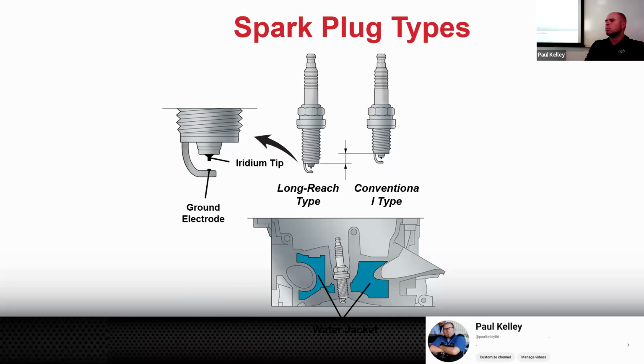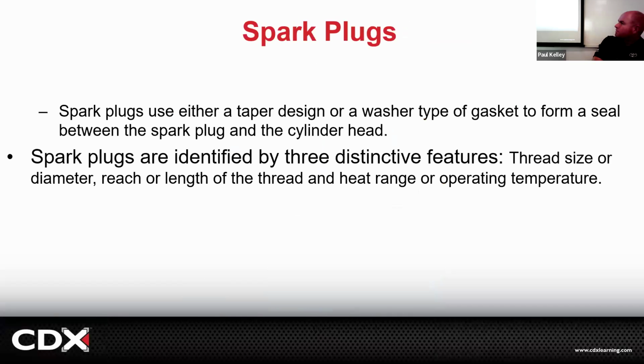So when people say, oh, it's just spark plugs, it's easy. Well, there's a lot of things that could go wrong with changing spark plugs, especially if they're the wrong parts. That's really scary, right? And then also they have heat range or operating temperature. So there's colder plugs and warmer plugs. I'll show you a little slide as to what the difference is.